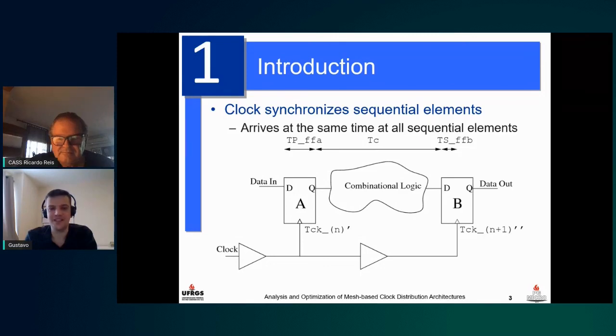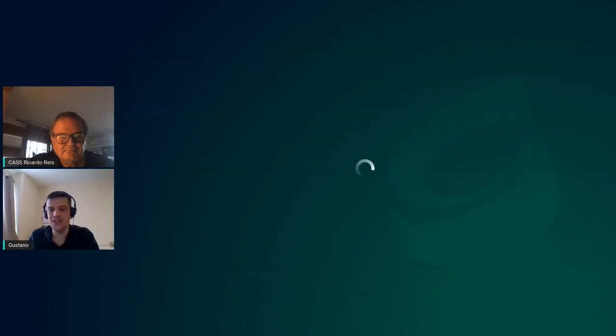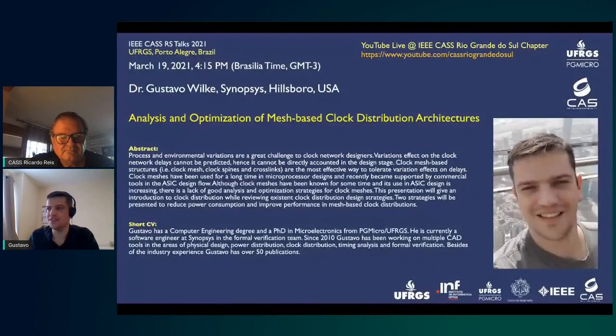The 20%, I got the number at the time from the literature and from some data that I had from circuits that I was working on. But I don't know what this number is today. I think the idea of analyzing the clock network is that you want to get as accurate an analysis as possible so you can reduce the guard band.